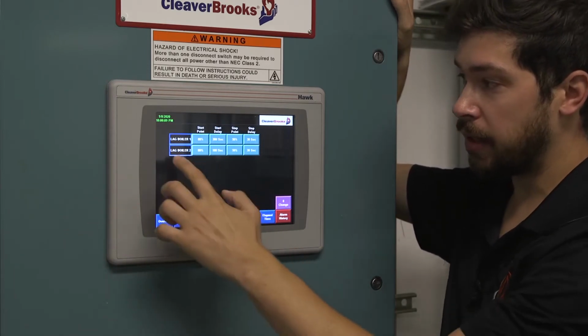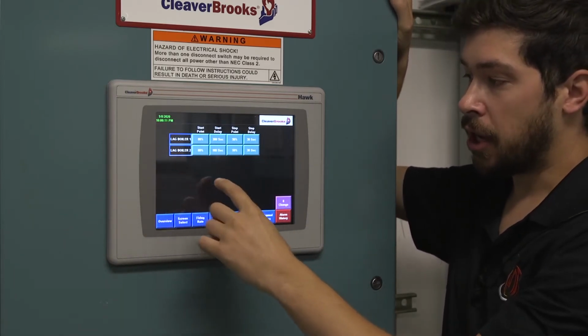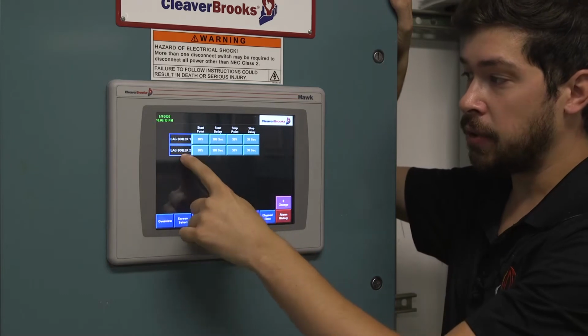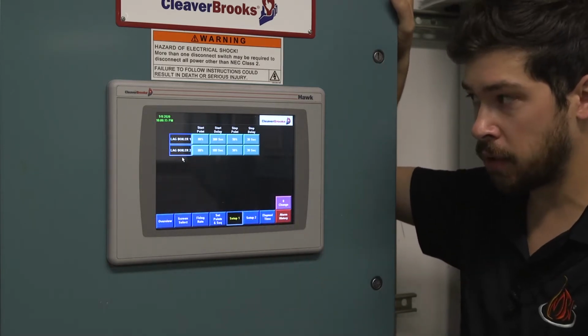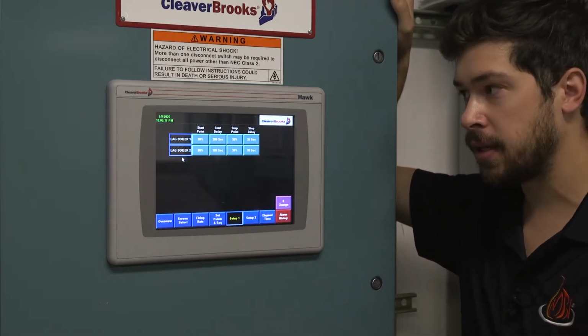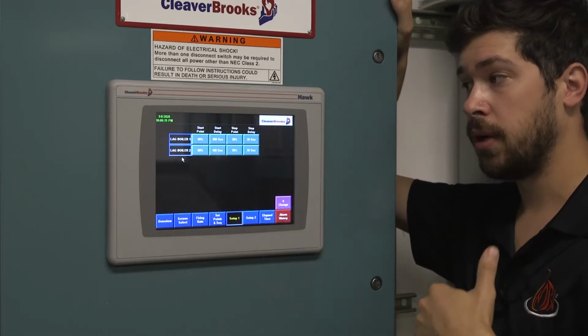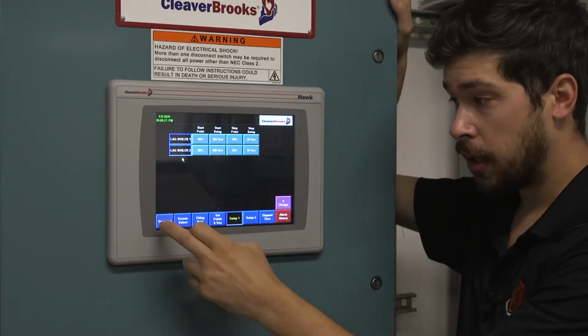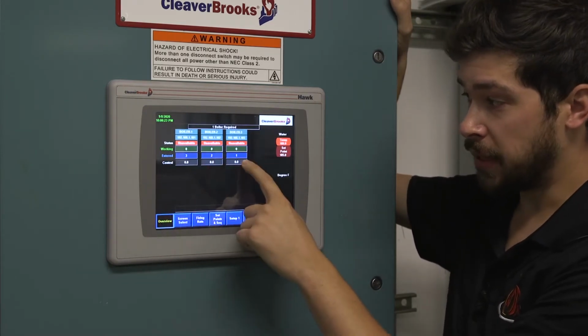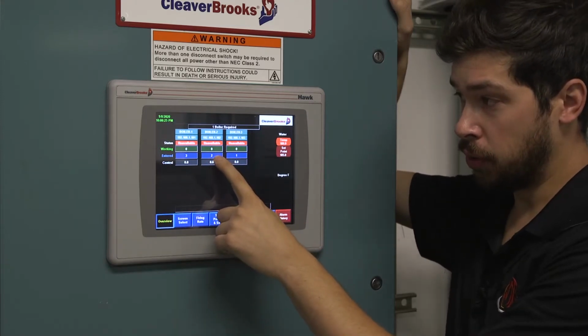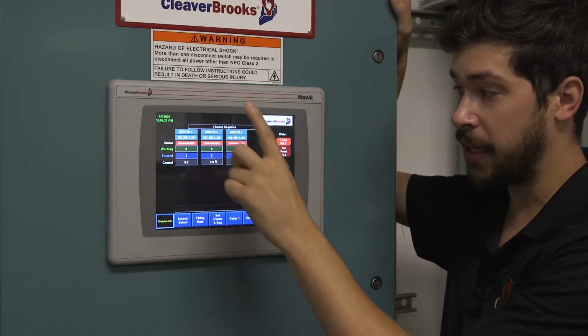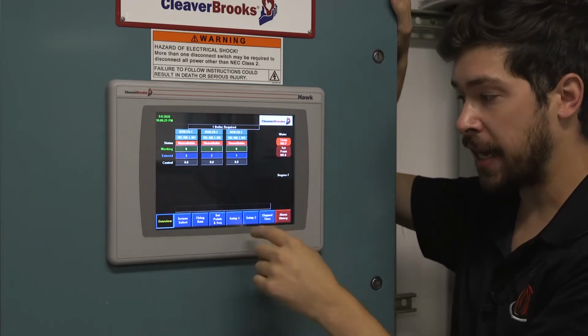To make a little bit of sense of this, think of it, these are the 2 lag boilers. So the lead boiler is of course whatever boiler's running first, and then lag boiler 1 would be that number 2. If we go back to here, this would be the lead boiler. 2 in the control sequence would be lag 1, 3 would be lag 2.